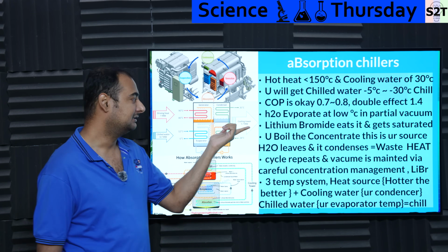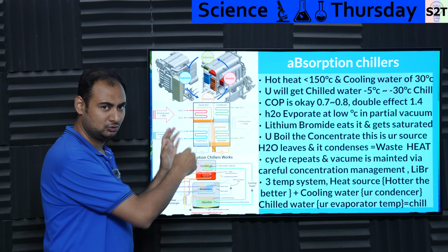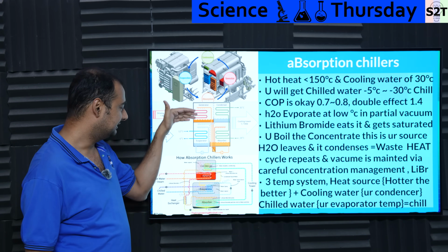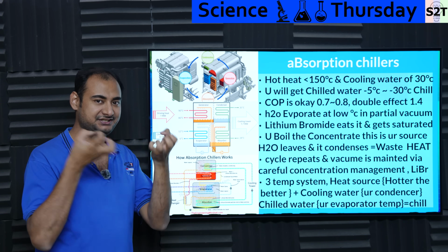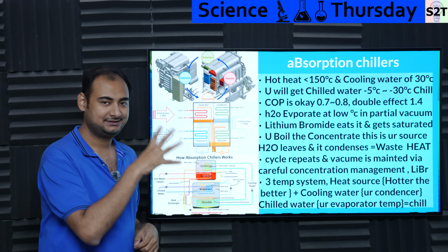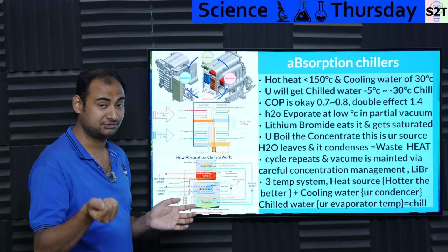So to say. And how do you achieve this? Well, you take your chilled water that is running on a loop. In that loop, you spray water onto it, distilled water. You spray that water and that water goes onto the pipe and leaches heat from it. But this area is partial vacuum, so it boils. Basically, the liquid to gas phase change happens. Now you have vapor pressure.